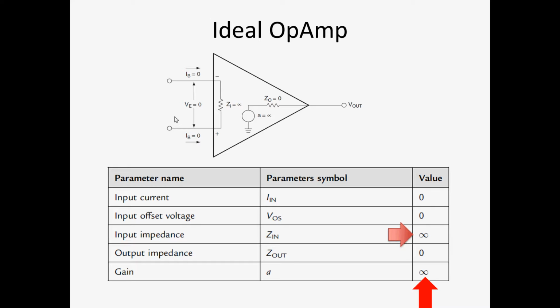And at some point, this could be comparable. So going back to the stimulation, because it's the same thing, the stimulations are actually driven by an amplifier. So they are at the other end of an amplifier. And the reason why you want zero output impedance for an amplifier, or infinite drive, is because you want to sustain that current or voltage no matter what you connect to the amplifier.